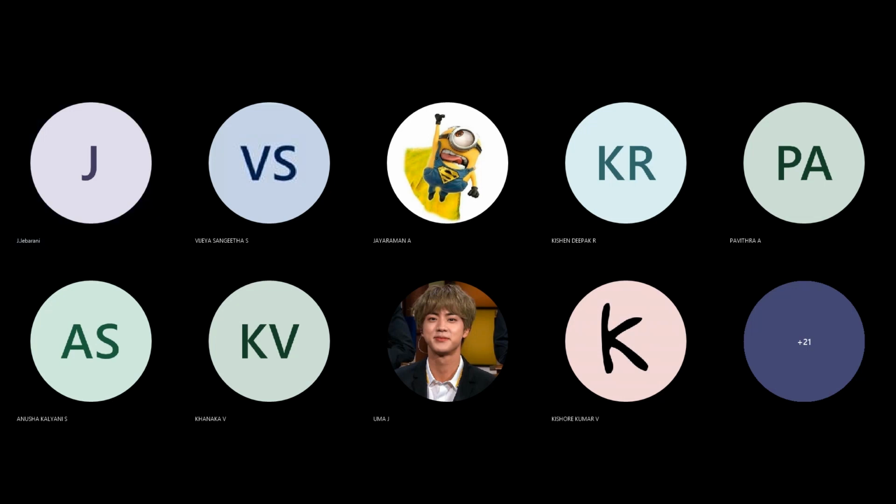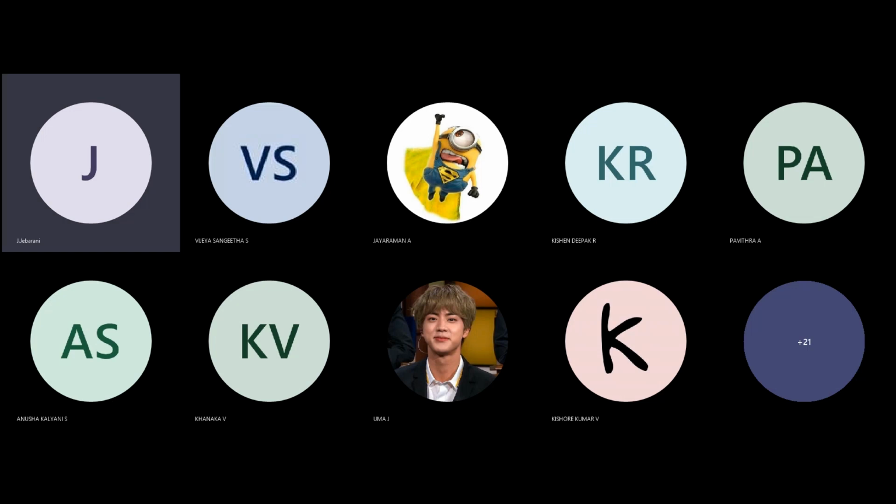It is multicolor molding in which various kinds and colors of resins are injected from the injection units and enter into the molten resin mixing manifold. In the manifold, a compounded or layered flow of various kinds or colors of resin is then charged into the mold cavity to form the multicolor product.